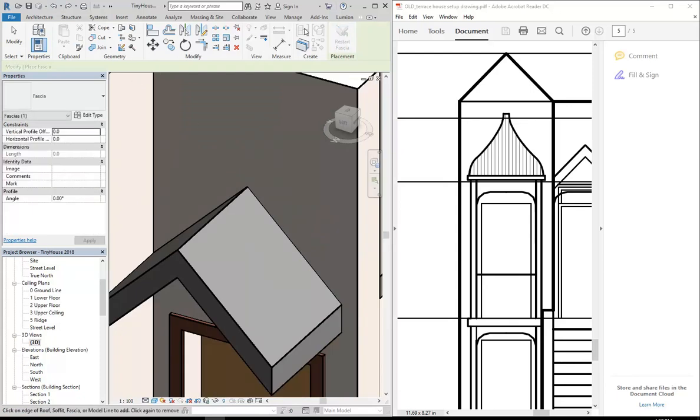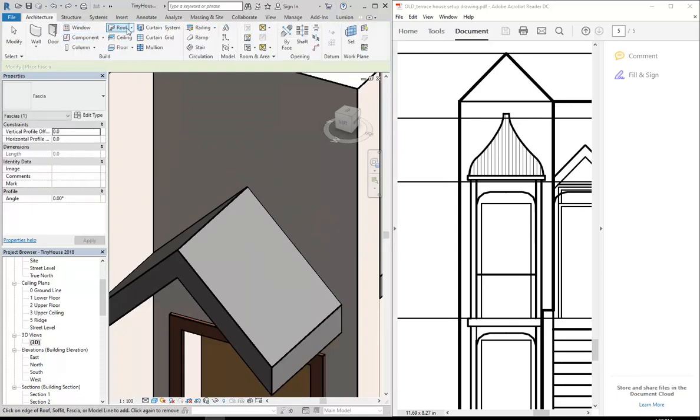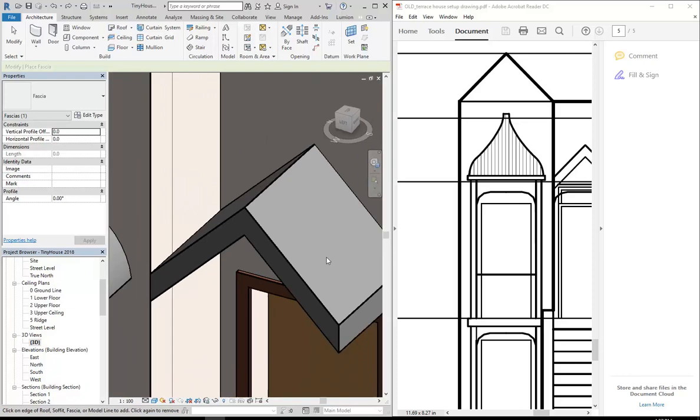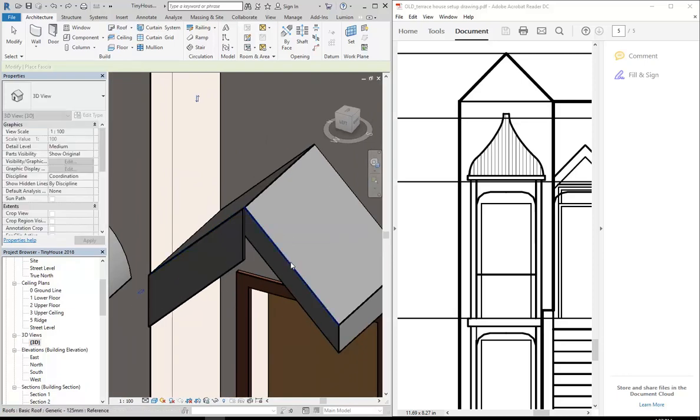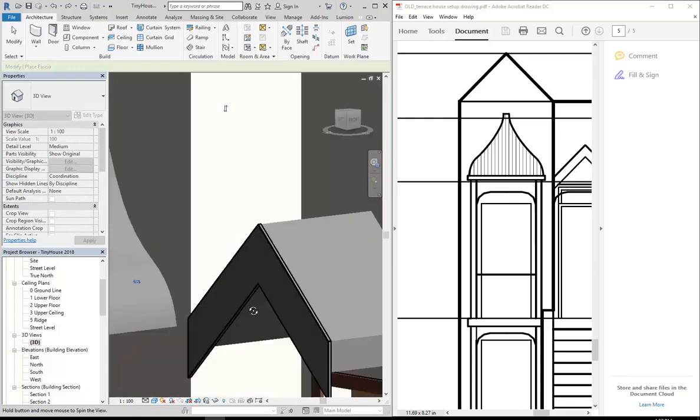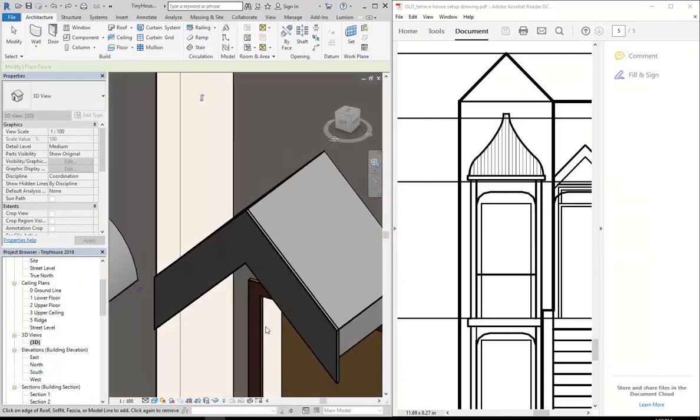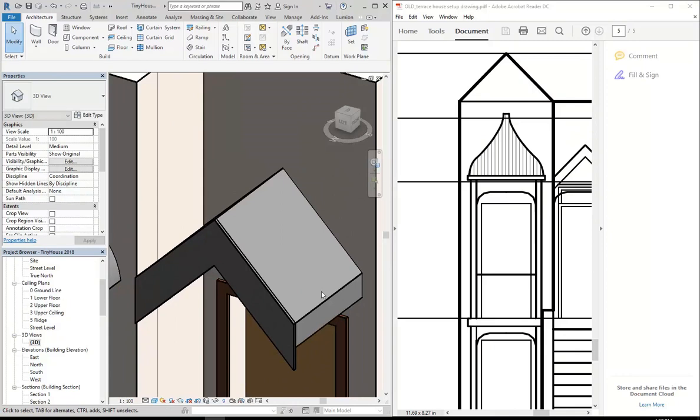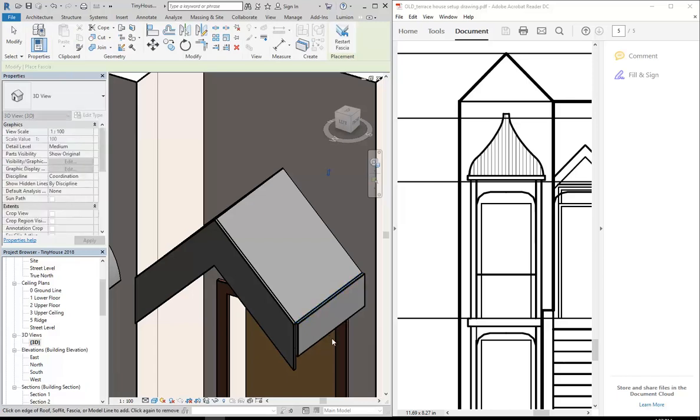So again, using that menu to go to the options under roof, and then roof fascia. So this time I'll choose the front. And then the other side. So that puts a nice barge board on the front. But I'm going to cancel that now and then start again, roof fascia, and then choose the side separately.